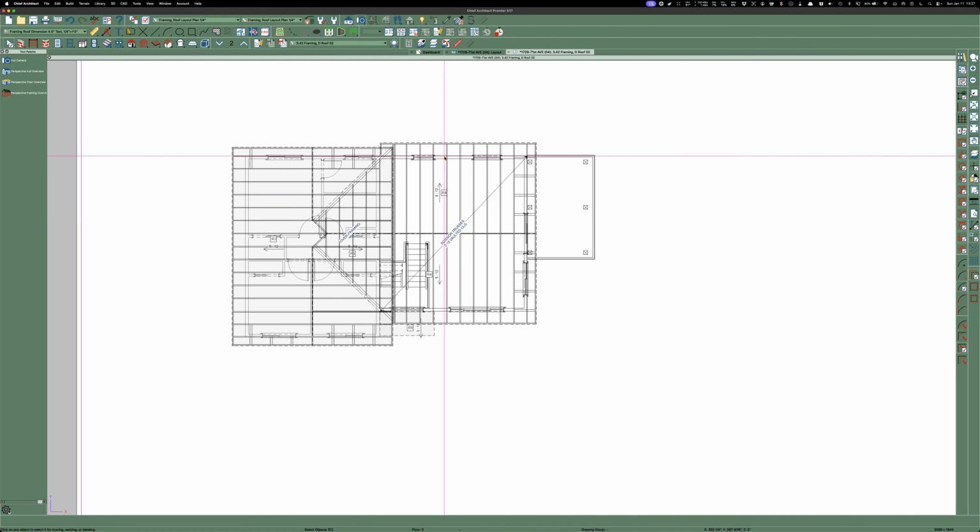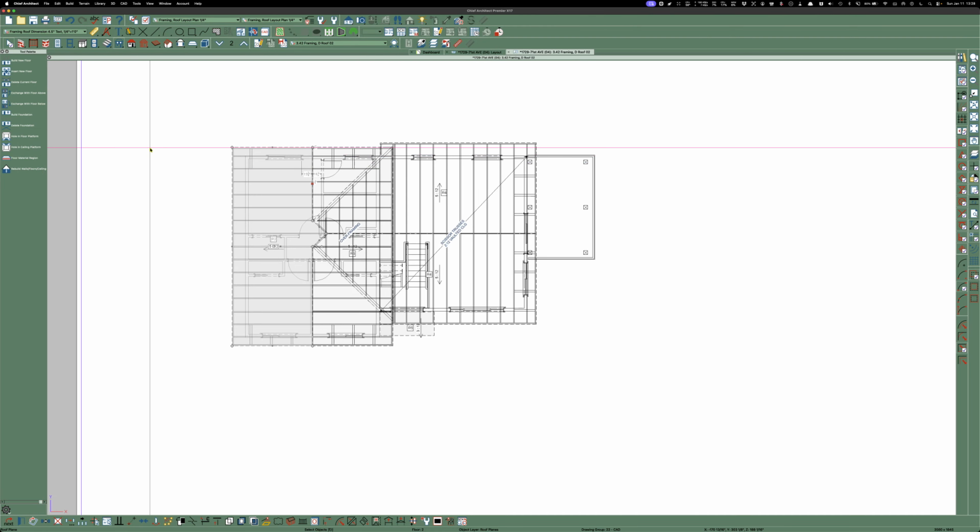And when you redraw something, whatever this room in this general area is, and you draw it a different shape, when you go to check the room dialog, you'll be surprised that it'll be like bedroom 2. You're like, whoa, wait a second, what happened? So I think the only way to get around that is when you go here and you actually delete an entire floor. That might take care of that.